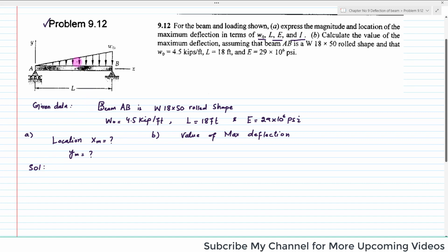So the first step of solving this problem is that you have to draw the free body diagram of this beam. So let me draw this free body diagram. This is the beam, this is point A and this is point B. At point A there is a pin support, so we will remove it and there will be a reaction force, and again at point B there will be a reaction force B. Clear? Now you can see that this is a uniformly increasing load. Clear? So this is W0.